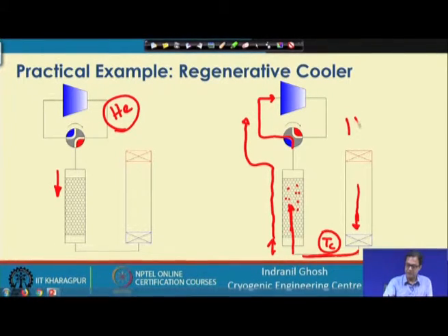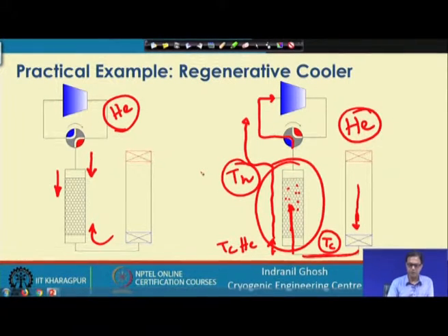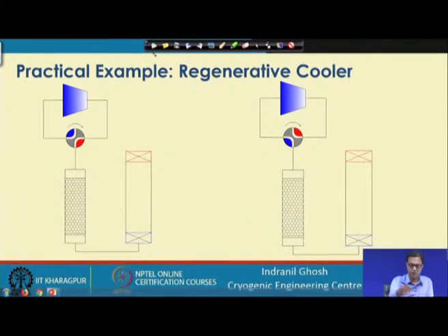Helium is the gas passing through this regenerator, which is our concern at this moment. In one cycle pressurized gaseous helium flows through the regenerator, and in the other cycle the low pressure, expanded helium moves from Tc to Th in the ideal condition. This is the configuration of a fixed bed regenerator, and the principle of working in the pulse tube refrigerator operation. This is the basic pulse tube configuration.